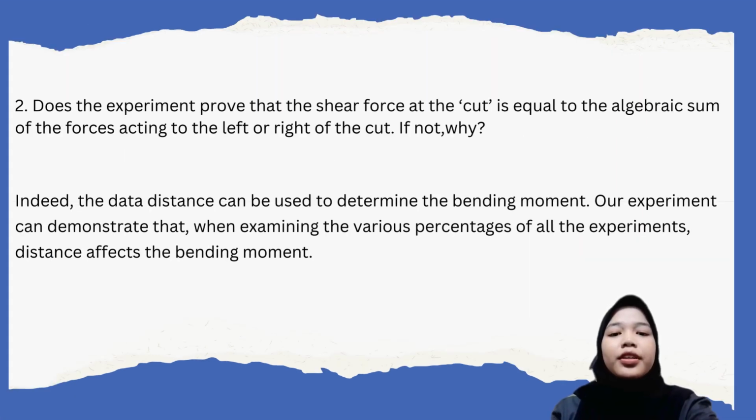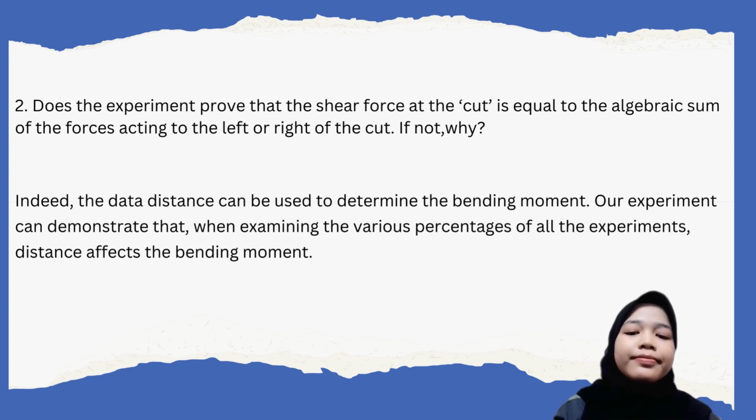The experiment demonstrates that the shear force at the cut is equal to the algebraic sum of the forces acting to the left or right of the cut, and that distance affects the bending moments when examined at various percentages.